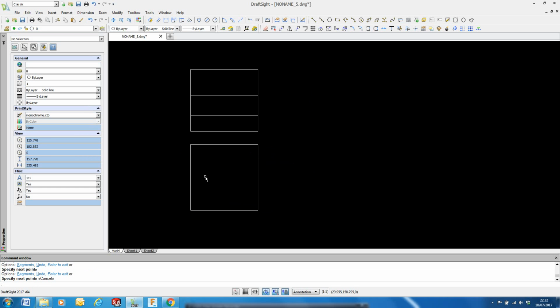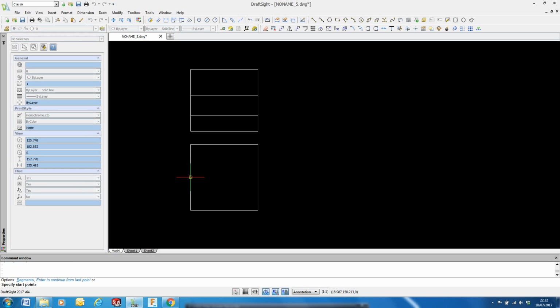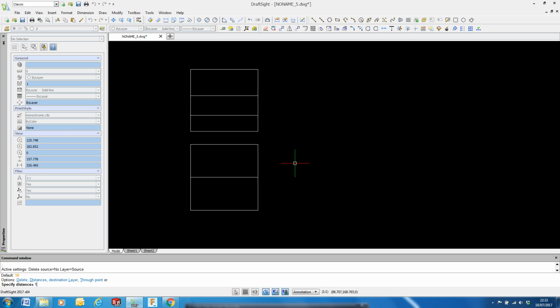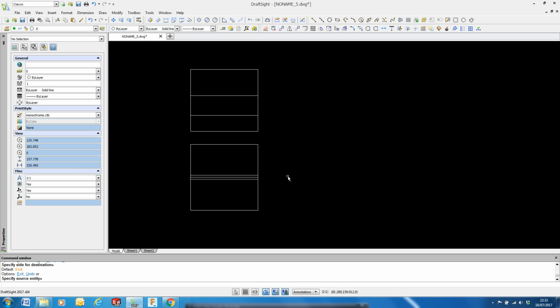And if we think about what we're seeing on this top view, we see the very narrow groove in the bottom, the 3 millimeter wide groove, and we see the edges of the V. So my initial technique might be to draw midpoint line, and that is exactly in the center, and I can use my offset command. 1.5 is half of 3, so I can have that line going up and I can have that line going down. That gives me my 3 mil overall.